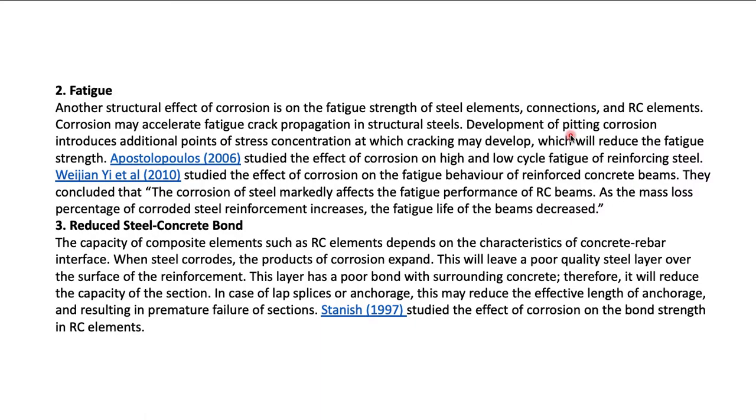Studies examined the effect of corrosion on high and low cyclic fatigue in reinforcing steel. Wilson and others studied the behavior of reinforced concrete beams and concluded that corrosion of steel markedly affects the fatigue performance of RC beams. As the mass loss percentage of corroded steel reinforcement increases, the fatigue life of the beam decreases.